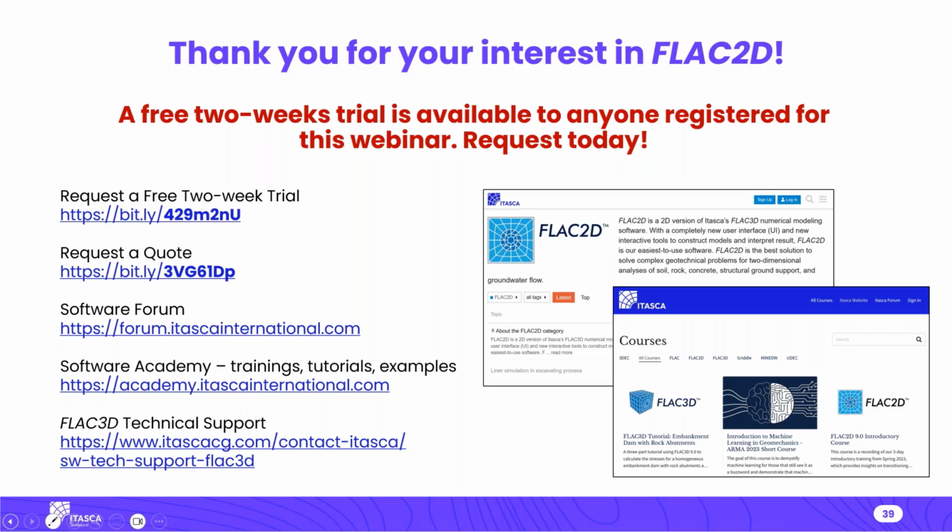Great, thank you, Andre. And last question for today's webinar. Can we write code in Python to build and run a model instead of FISH? If yes, do FISH operators work in Python? In general, you can build a whole model in Python. You will probably have to run certain commands or FISH from Python. Pretty much there is a way to execute commands and FISH from Python. And I'm sure that there are plenty of examples in our documentation. I didn't provide any examples in this presentation, but in general, the answer to this is yes, it's doable.